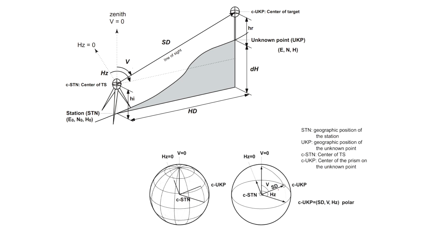Okay. So, basically what we are doing is we are taking the measurements in this circle, as well as vertically we are also measuring in this circle. So, the horizontal will give you this angle, because you are not moving in the same line, you are moving at different points also. That will also be taken into consideration, as well as the vertical angle, and that is your slope. That will also change depending on the elevation change here.